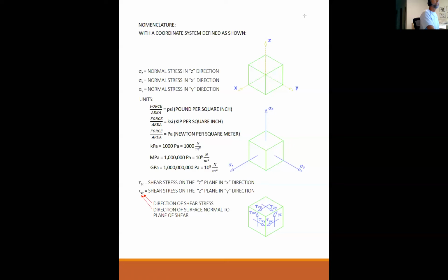Let's say you have a support and you have a steel rod hanging from that support. And then hanging from the end of that steel rod, you have some mass, some kind of weight. If you solve for your reactions, you're going to find that this rod is in tension, and that's it. There's nothing else on it. There's no bending moments and no shear.